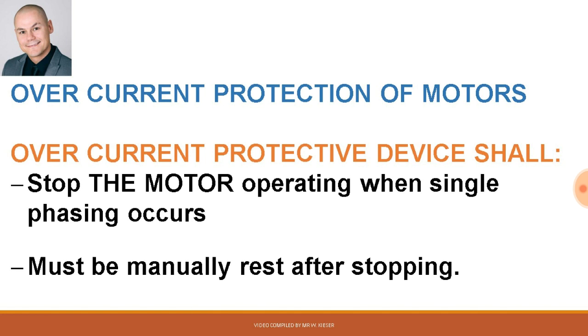In terms of overcurrent protection of motors, SANS 10142 stipulates two requirements. The overcurrent protection device shall stop the motor operating when single phasing occurs and must be manually restarted.